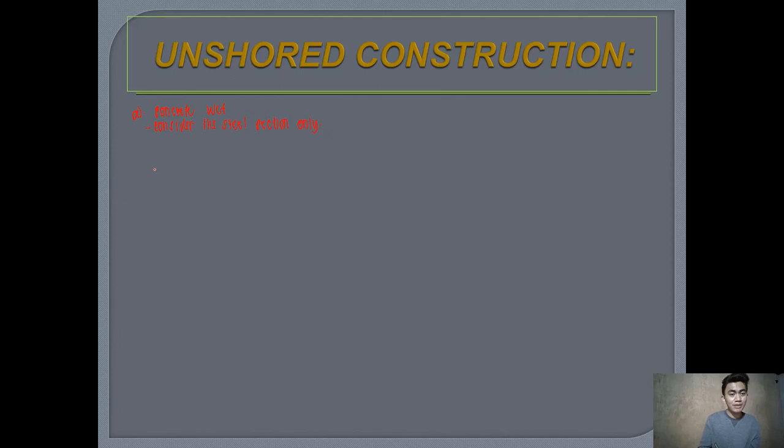Now, if we are going to consider the steel section only, what will happen? We need to determine again the moment of inertia. This time, we do not have a concrete slab attached at the topmost part of our steel section. So what will happen to the stress? We will only determine stress for steel. No need to determine the stress for concrete since we are only considering the steel section.